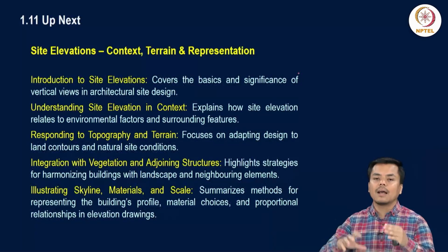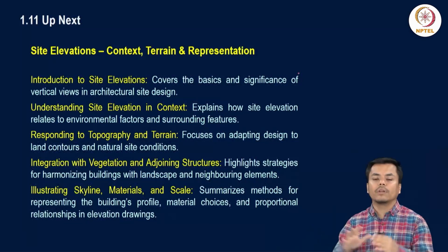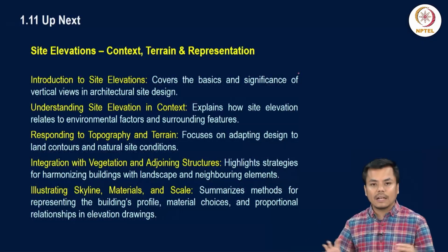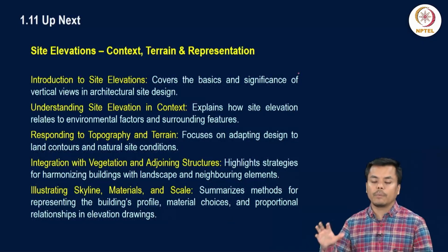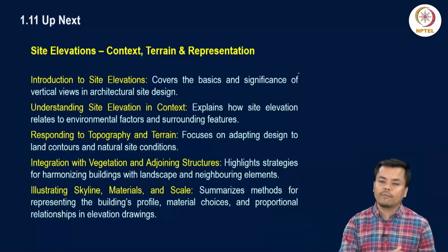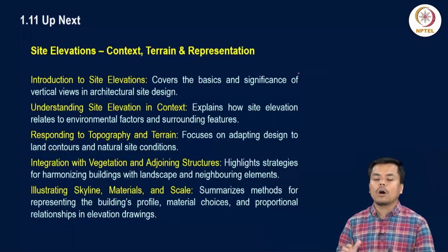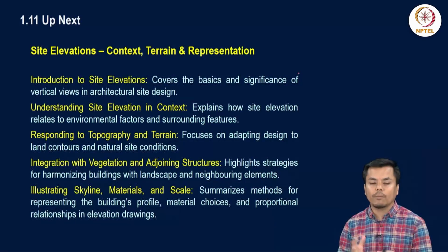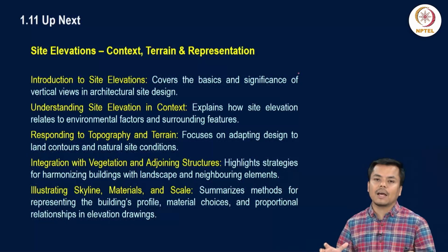To understand the scale of the building and of different spaces within the site, site elevation is very important, and especially if the site has a slope or contour, site elevation provides much understanding about the entire site plan in totality. So that is why site elevations are important.